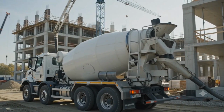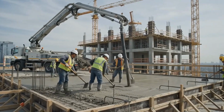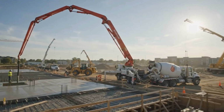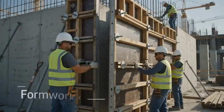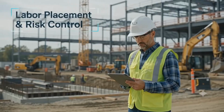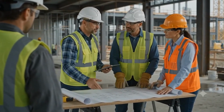Concrete is the backbone of structural estimating. It is one of the most volatile divisions on a project bill of quantities. Market fluctuations can break a project's budget instantly. Estimating Division 03 isn't just ordering mix. You are actually balancing 3 simultaneous trades inside a single scope. You have formwork measured in SFCA, reinforcement in tons or pounds, and ready-mix concrete in cubic yards. Combine all 3 with your labor placement crew. Miss any single element, and your structural budget falls apart.